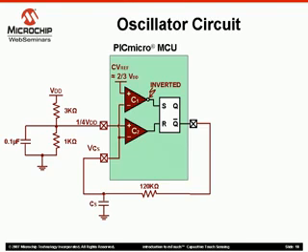Comparator 2 will need an external reference. Therefore, we use a simple voltage divider to produce a voltage of 1/4 the supply voltage on the comparator's non-inverting input. The 0.1 microfarad capacitor is added to reject high-frequency noise from the power supply and ensure a stable lower limit voltage.